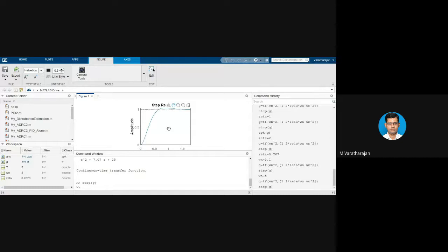Usually in time response, we consider rise time, peak time, settling time, sometimes delay time also, but usually maximum peak overshoot and settling time are enough. So this is the fourth analysis, that is to analyze the variation of omega n in the time response.